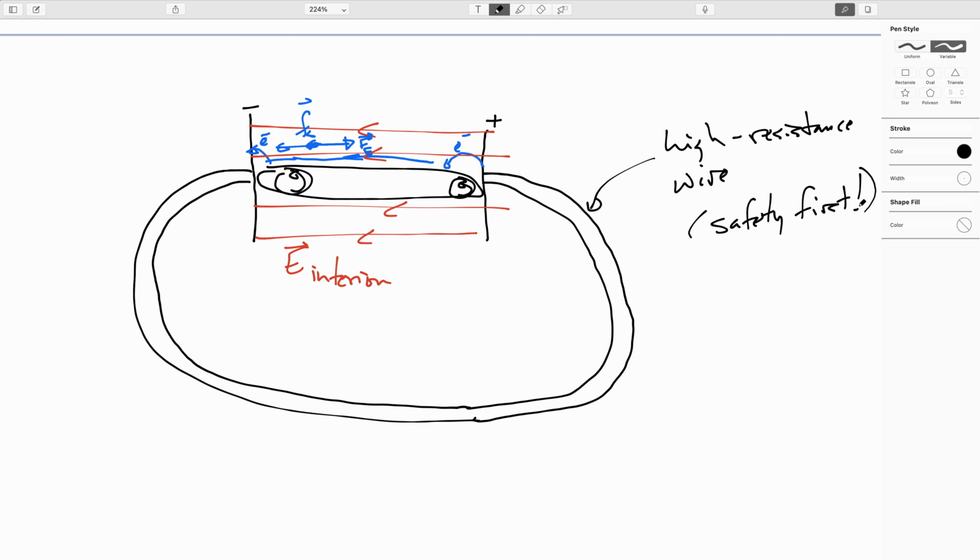It's again designed to protect against just such kinds of things happening. If that short circuit had run for much longer, there's a very serious risk of actually boiling the chemicals inside the battery and having a potential explosion of the battery with acid flying all over the place. It would not have been a good thing. So if you're going to try to do this at home, do not use wire. In fact, just don't do this.